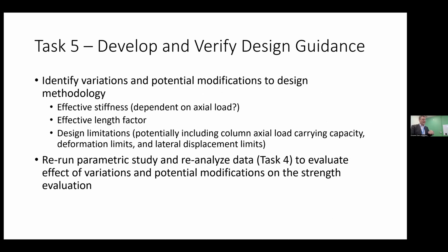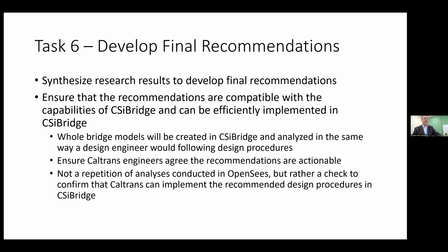Okay, so that's basically tasks 1 through 4. That's pretty much where we are, and then the future tasks 5 and 6: develop design guidelines, looking at effective stiffness, effective length factors, or K, and design limitations. Then develop final recommendations, and ensure that those recommendations are compatible with CSI Bridge, so they can be efficiently implemented within that software. It's not meant to repeat analyses from OpenSees, but just to make sure that the design procedures can be accommodated within CSI Bridge.